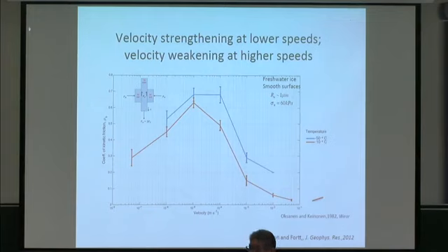For if we take, at low normal stresses, the ratio solely of shear stress to normal stress, and there happens to be an intercept in the Coulomb's law, then you're going to get a slope that's much greater than you would get from the tangent to the curve. And you could be misled by taking simply the ratio of those two stresses under low normal stresses. These are taken from the slope on the curve.